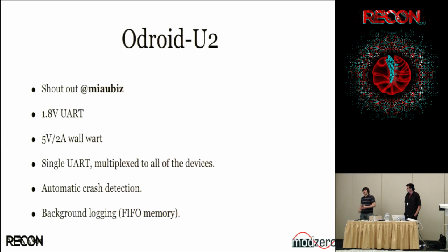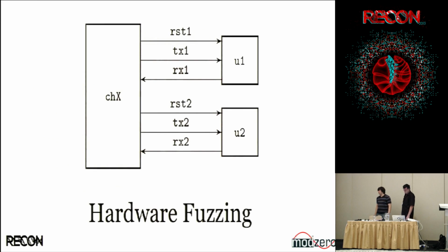I can now write an interface for a device like this, basically a UART, and it can log in the background. I can even disconnect the PC, and when I come back and connect the PC, I can ask what went on while I was away, and you can see kernel oops, kernel oops, kernel oops. Okay? So this could look something like this.